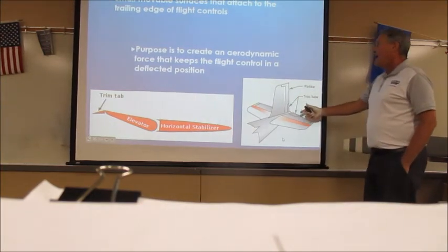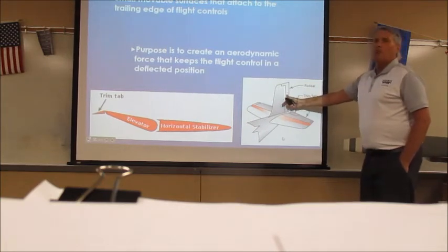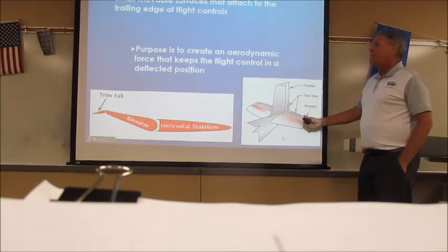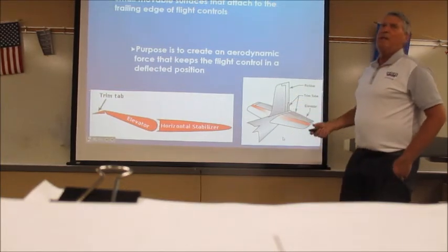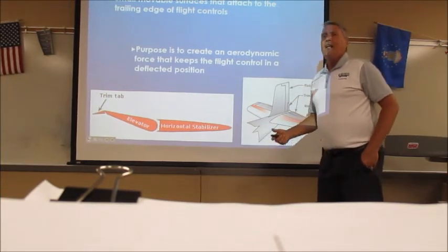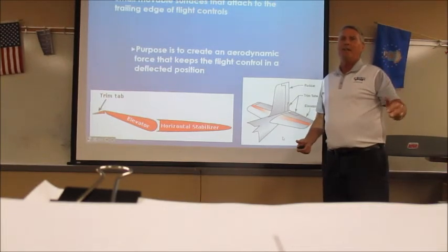You've got trim tabs, you can have them on your elevator or on your rudder right here. Elevator trim tabs, rudder trim tabs. It's all to help us fly nice and level and take the fuss out of always having to keep your hand tightly on the yoke.